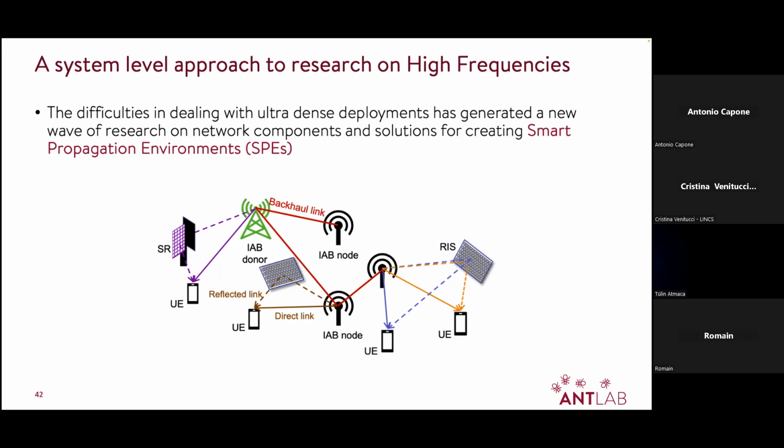Or you can have reflective intelligent surfaces, which are antennas, passive antennas, that just reflect the signal, but reflect the signal like an antenna, right? It's like an array of antennas. So they can be configured in order to change the characteristics of the reflected ray, and configured again by remote. So you have a separate control plane that can be used with a frequency which depends again on how many frequent changes you want to make to the configuration of the network that can change the behavior of a reflective surface. And there are others. For example, you can have smart skins that are static surfaces, which are based on metasurfaces, materials that are maybe kind of the evolution of the mirrors, not just the geometric optics, but something that can be a little bit modified based on the characteristics of the surface that you use.